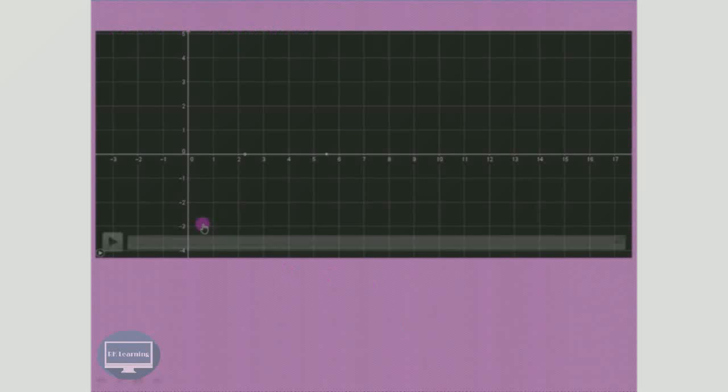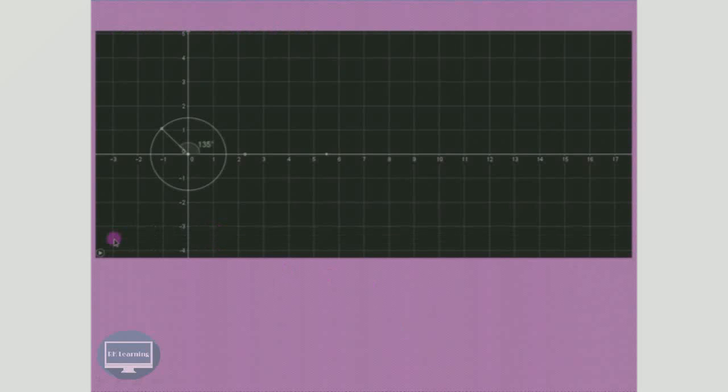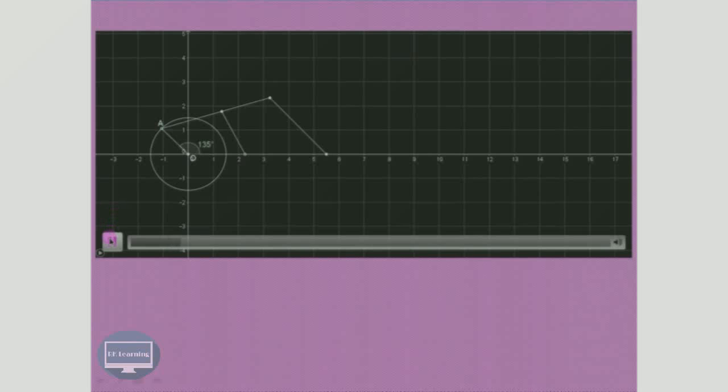As we have already seen, we have chosen the space diagram scale as 1 centimeter is equal to 100 mm. So, using that particular scale, we have drawn this particular space diagram. So, this is 1.5 centimeter, this is 4.5 centimeter, and like that. As the crank is rotating in the clockwise direction, the velocity of A with respect to O will be perpendicular to this and in the direction of rotation, that is clockwise.